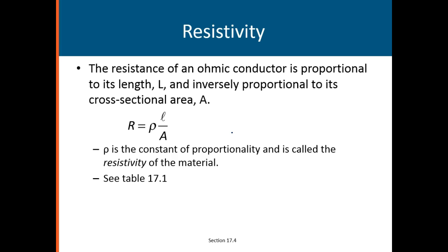So here's the other deal, folks. Resistance varies with length, cross-sectional area, and stuff. Resistivity of a certain material is always going to be constant. It's a characteristic of the material. So that's why we would ever want to use resistance, it fits Ohm's law like a glove. We don't usually want that, but if we do want to compare it to other materials, we want to look at resistivity.